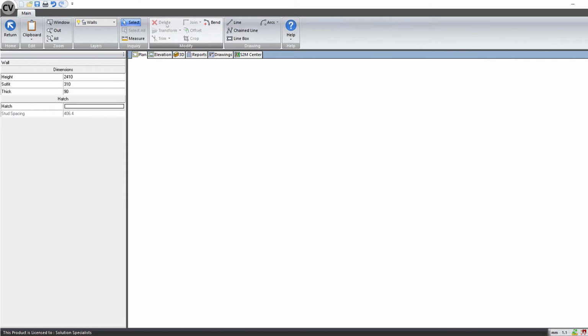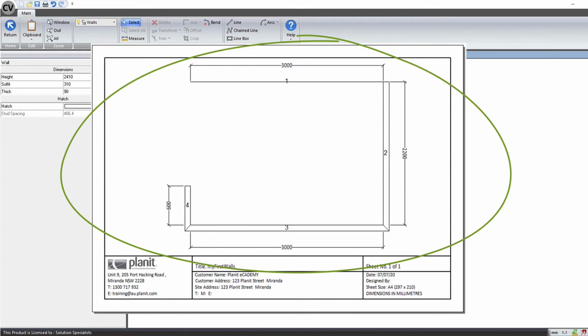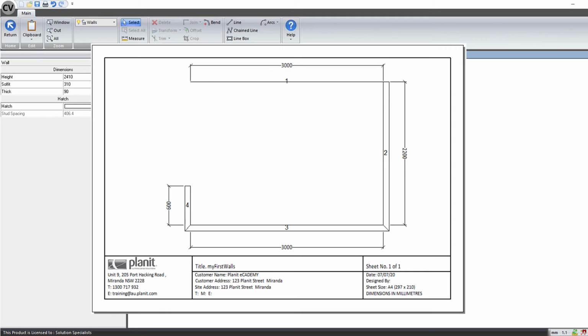There's a 100% chance you'll need to draw walls at a certain size. Randomly clicking in the right shape of the room just isn't going to cut it. We'll take a look now at how to draw a room and get the sizes to be exact. Rule number 1 of drawing our room is that we always need to draw the walls in a clockwise direction. This ensures that our wall thickness is allowed for on the right side of the line.